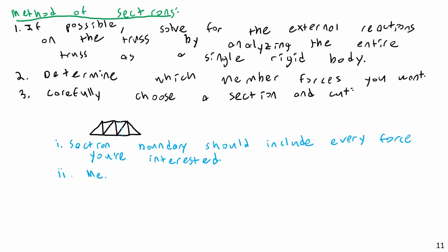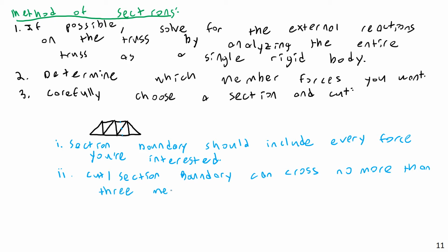2. The member cut, or the section boundary, can cross no more than 3 members. So I can do something like this, and that would be fine.